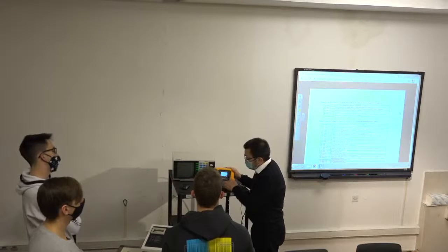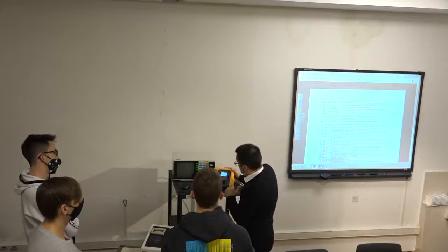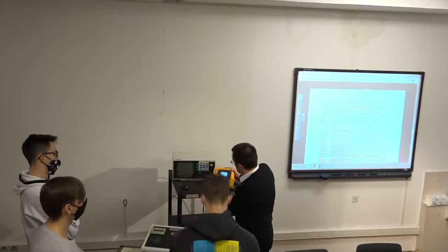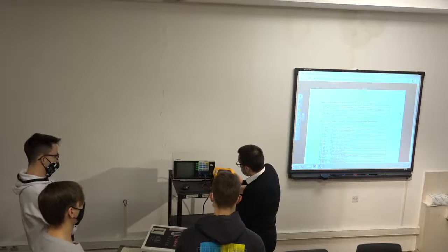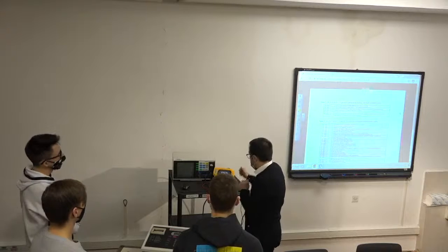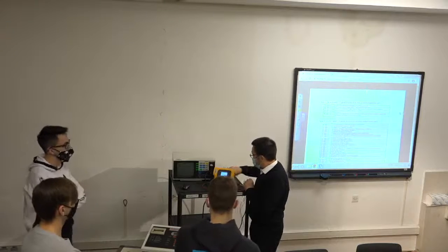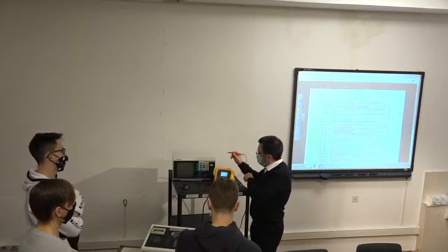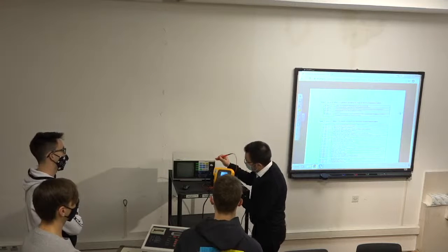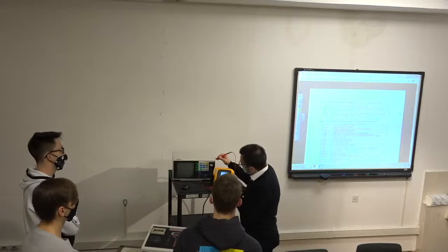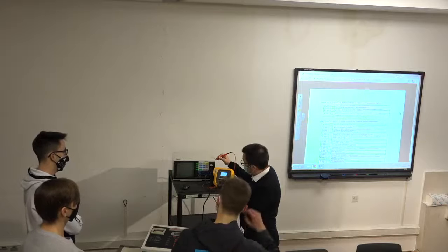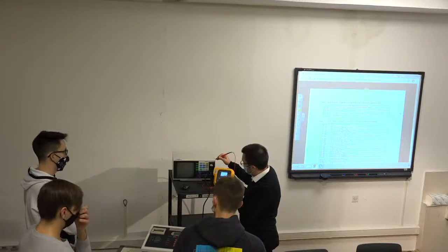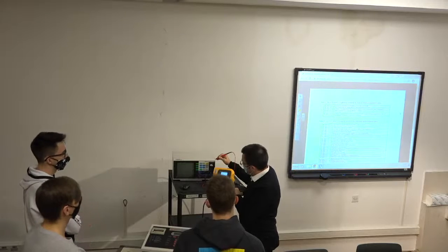So these are these tests, and then again, not to keep you too long, now we have the protective earth resistance. What we are looking for here is actually the resistance of different points that we have on the housing. These must be low, so it should be under 1 ohm.